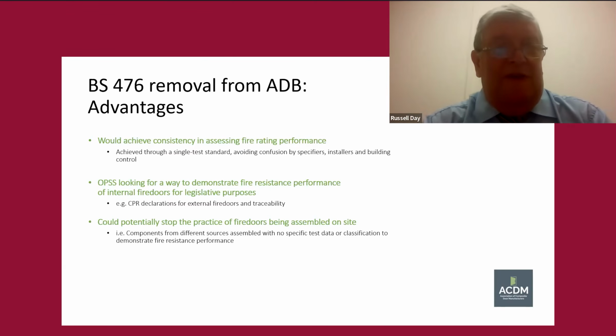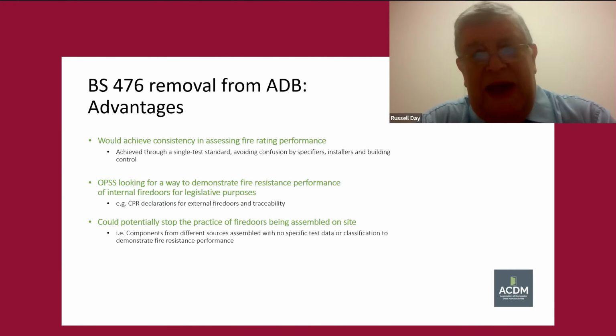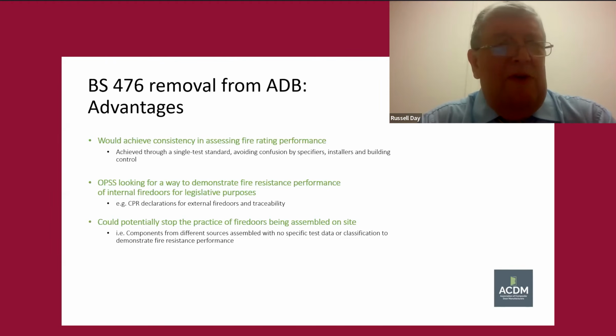So there are some advantages. We would achieve consistency in assessing fire rating performance. One of the issues that Judith Hackitt came out with was that there's a lot of confusion in terms of approved document B, and this is just one of them, the fact that we have two methods of complying to a single requirement. So one can see that would clarify things for them.